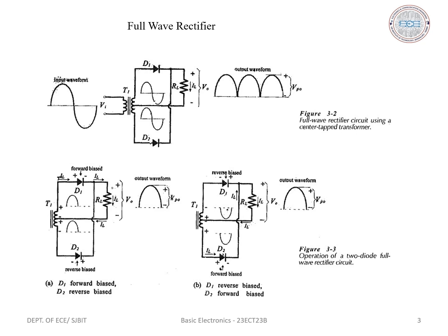Hence, it is called a full wave rectifier. Now, if I connect a capacitor in parallel to the load resistance RL, let me name it capacitor C1. C1 is added to ensure that the output voltage remains the same or near the peak voltage even when the diodes are non-conducting. It charges to approximately 16.3 volts at the peak of the positive half cycle and holds the voltage at this level when the diodes are in their non-conducting states.